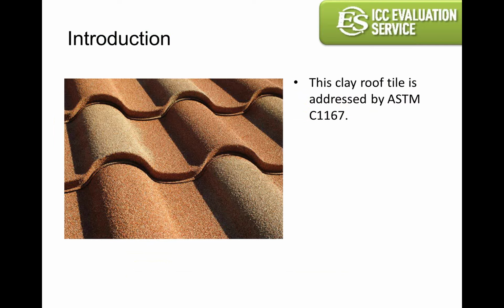An example of just a basic product, clay roof tile. The code gives some prescriptive requirements as far as the roofing requirements in Chapter 15. And just for the clay roof tile itself, there's been a specific standard for that product for a while, the ASTM C1167. Next slide, please.